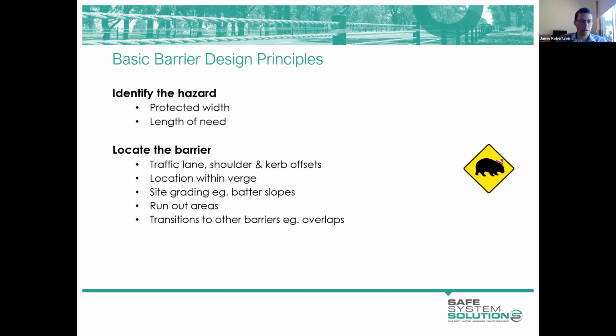Providing run-out areas. So that's a relatively flat, clear area near the start of a barrier that we like to provide, and I'll go into that in a little bit more detail shortly. Providing a run-out area might influence where our barrier starts and ends.